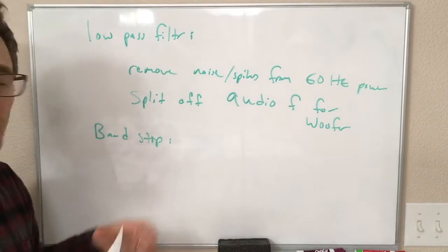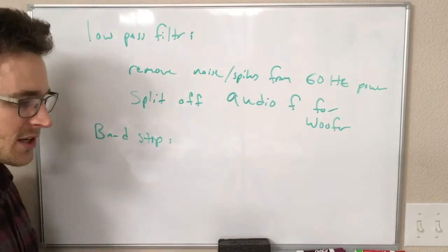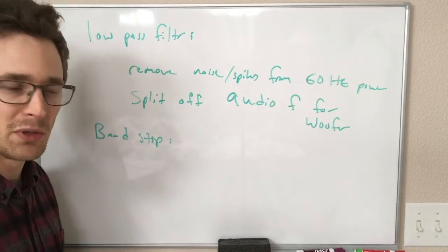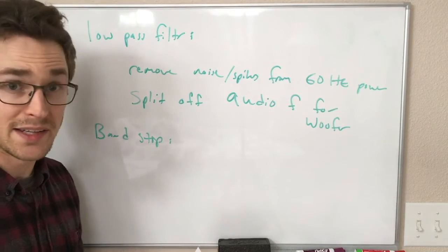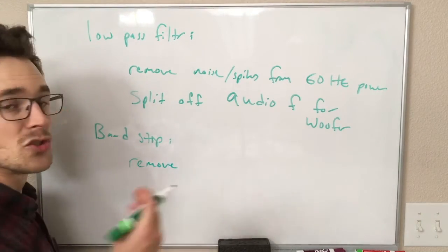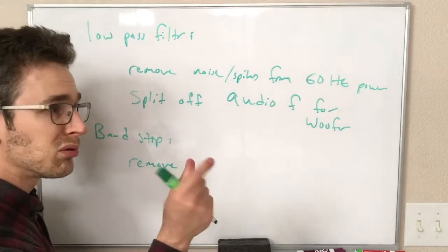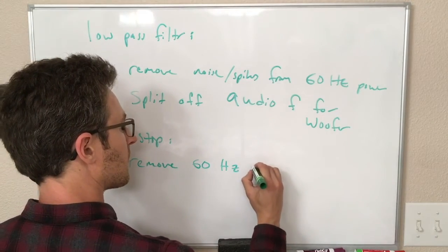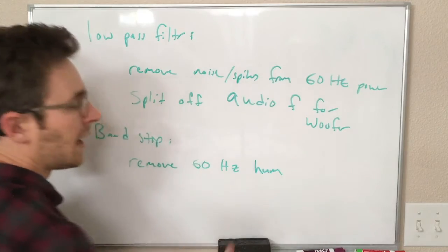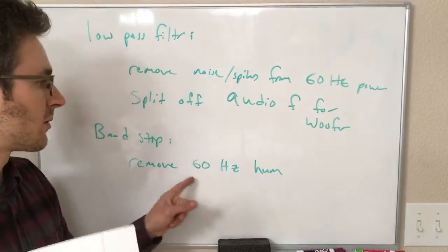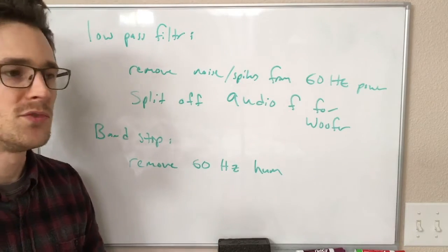Let's say I'm doing some sensitive measurement and I'm just seeing this 60 hertz signal on everything because my circuit's acting like a little antenna. I can apply a filter to that signal to just remove the 60 hertz, plus or minus 1 hertz. And the effect of that is that everything else stays the same. The gain is 1, but just around here, that disappears from the signal.